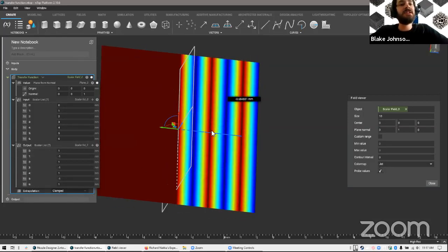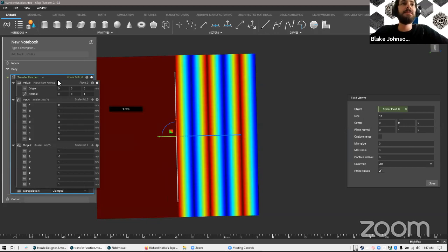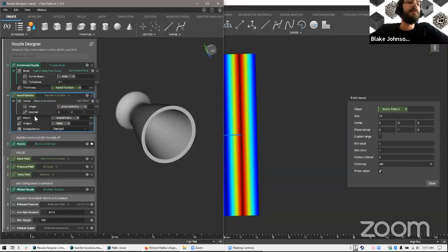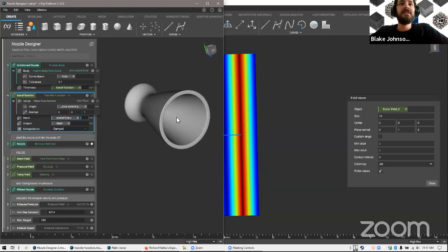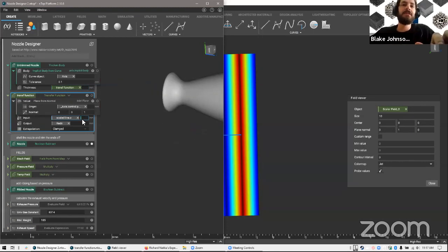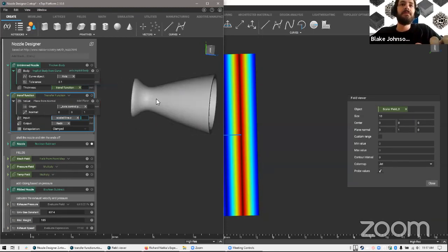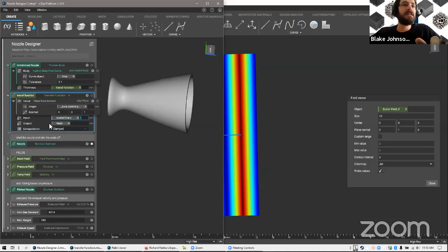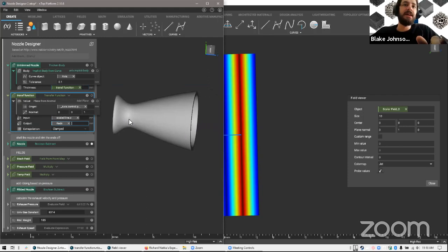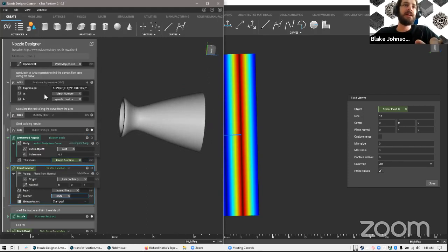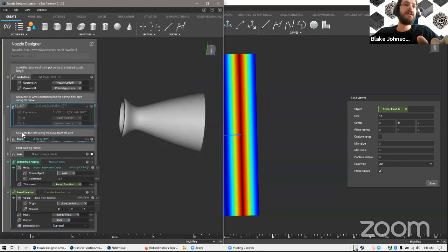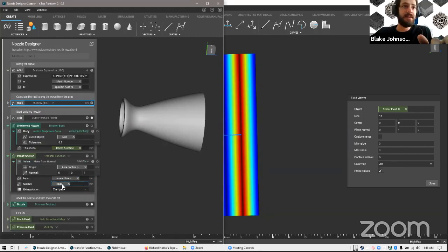And so you can imagine I did kind of a similar thing with my transfer function in the Nozzle designer. But what I put in is the points along the axis in the z direction. So you're basically just increasing linearly, 0, 1, 2, 3, 4, 5, 6, 7 to 10. And then I'm putting in the desired radii at these points all along the way, because I know that from calculating it based on this area equation, getting the radius, and then now I'm scaling up.